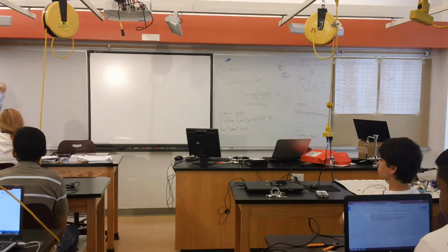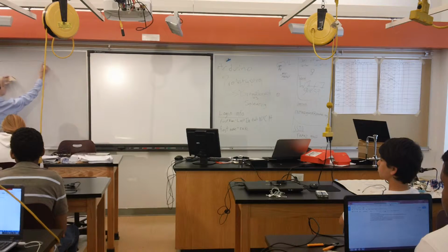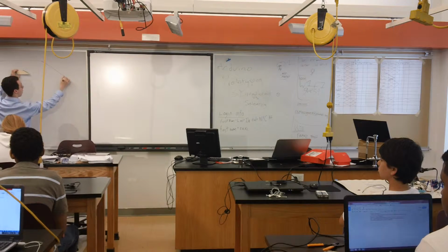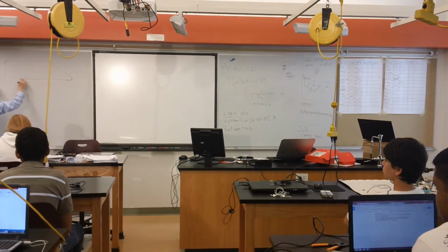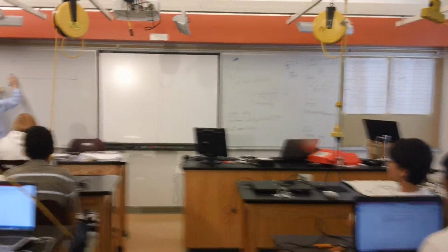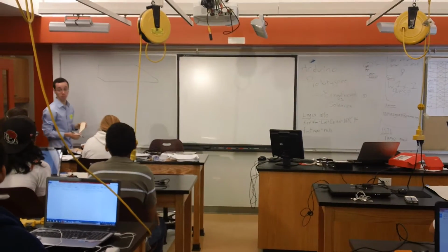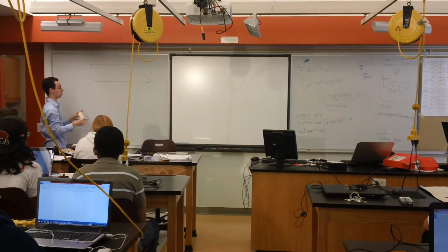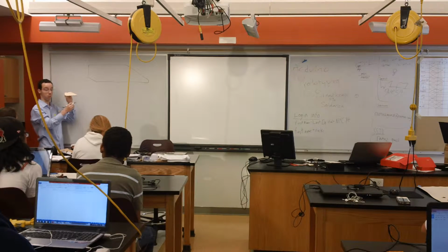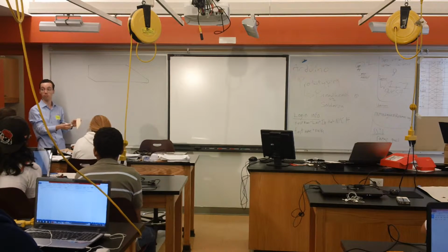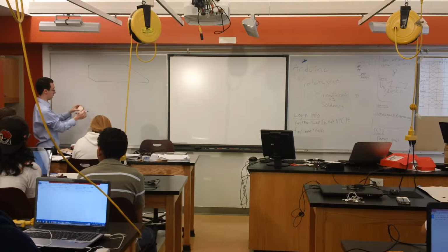So basically, the goal is we want to have all the information we need to make the part, none of the information that is extraneous that we don't need to make it, and have it be human readable so that a machinist can look at it and can only interpret it one way. So if they follow the dimensions, they can only make the part correctly. There's no multiple ways of interpreting everything.